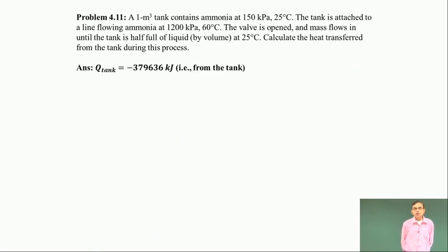The tank is attached to a line flowing ammonia at 1200 kilopascal and 60 degree centigrade. The valve is opened and mass flows in until the tank is half full of liquid by volume, at 25 degree centigrade. Calculate the heat transferred from the tank during the process. So, this is also a tank filling problem.